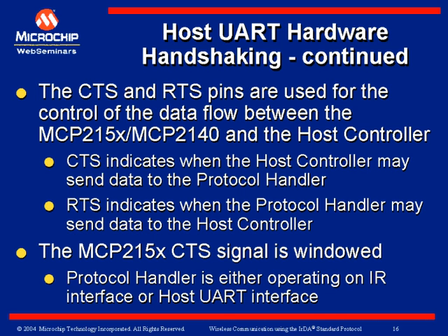Occasionally, the host controller may also be busy. It may be in a tight loop doing some operation where it cannot be interrupted. In that case, there is the RTS signal that can be used by the host controller to tell the protocol handler, don't send me any of the data packets you may have. And the protocol handler will then wait for the host controller to bring the RTS signal back low. If the RTS signal is deasserted for too long, while the data handler has data pending for the host controller, the link will be closed.